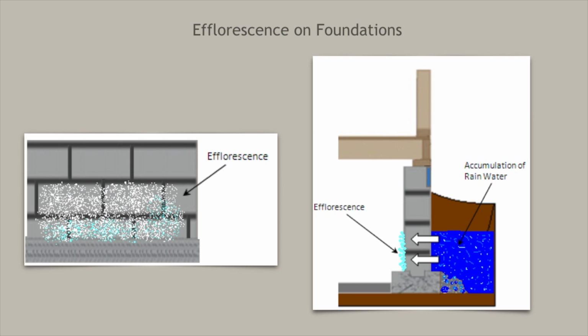As water lies against the concrete wall or block, a force is developed called hydrostatic pressure. This force or pressure pushes water and vapor through the concrete. Consequently, salt and lime are pushed through the concrete and deposited on the opposite side of the concrete foundation. This is called efflorescence, which is a salt and lime stain forming on any masonry product where water has pushed through. Efflorescence appears as a white or tan powder, which develops a surface thickness of 0.2 inches.